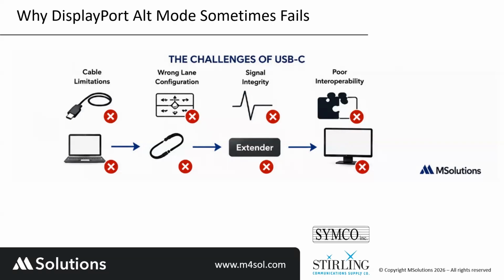Not every USB-C device supports DisplayPort alternate mode. That's something that you need to take with you. Not every USB-C cable supports DisplayPort video. And not every dock or extender or display supports the same alternate mode configuration. This is why I'm saying, and I will say it a lot of times, you must be able to test the configuration of the USB-C with the infrastructure that you're going to use in an installation or you intend to buy and use.